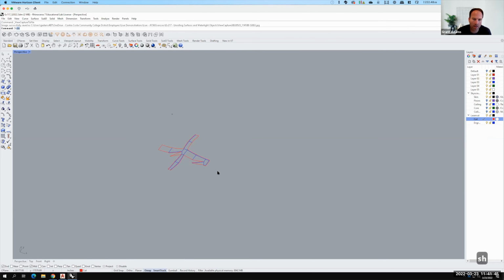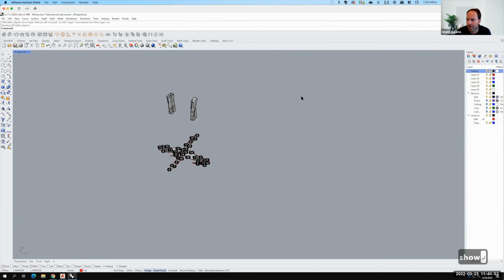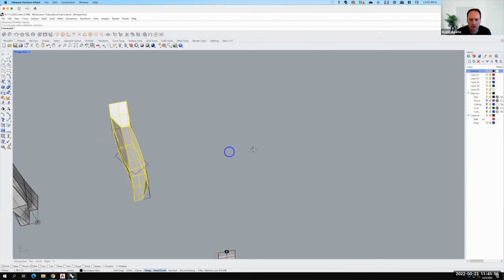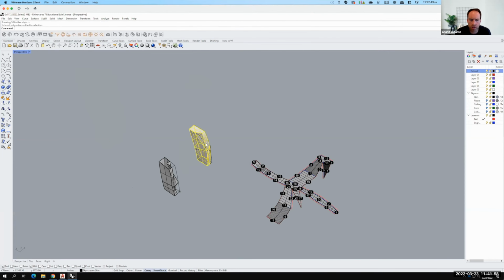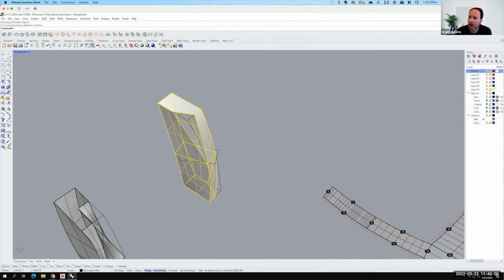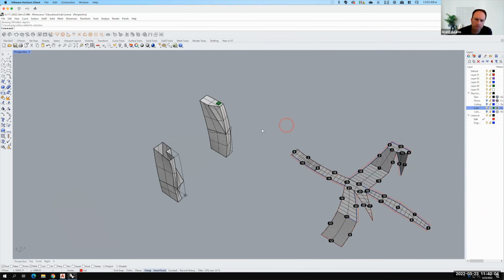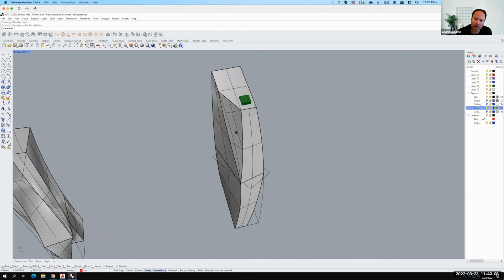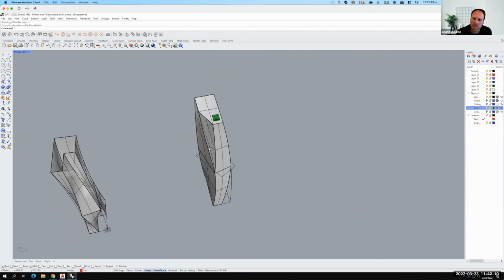And let's go into show so that I can see my other buildings here. We can turn back on my default layer. And let's work again with the skin of this building. So this is ultimately the one I want to 3D print. And I could leave the core on like that. And then I could convert this object over into something to 3D print.